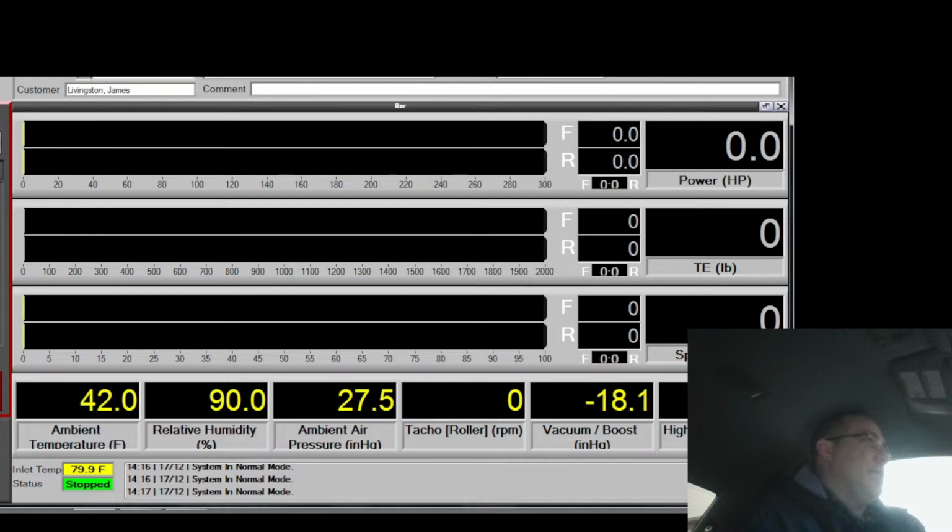So now we're looking at burn speed in units of time and not just in meters per second, because the flame front speed is still going to be whatever the flame front speed of ethanol is going to be, but my initial point is bigger and the distance I have to travel is less. And that means my cylinder pressure is going to rise more quickly than it would if I had the narrower gap.